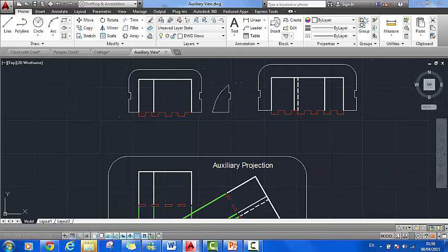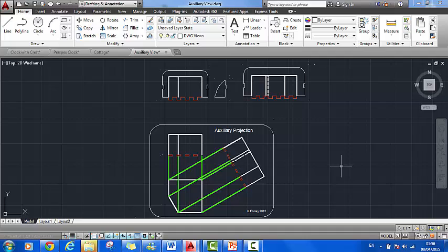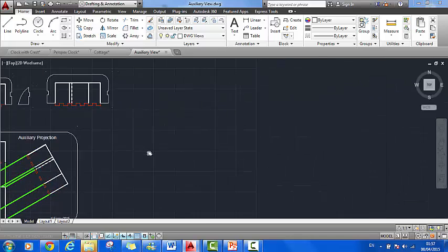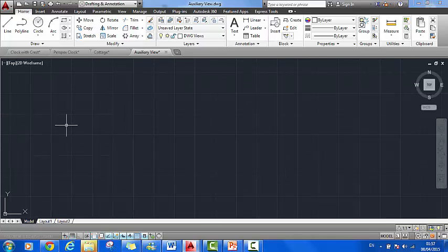The main and key skills involved in producing this resource are very few. We have the rectangle, fillet, creating angled lines, line types, inserting text, creating layers, and line thicknesses. Okay, so to begin, I'm going to create the base for this project. It's going to be 300 by 230.